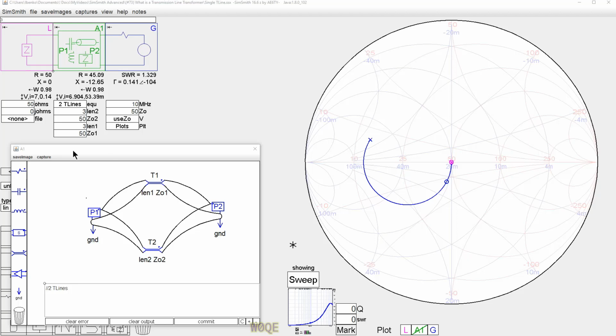The load impedance is set to give me no rotation. With a 25 ohm load impedance, these two transmission lines, 50 ohm and 50 ohm in parallel, give me a 25 ohm result, swept over frequency. So this acts as a 25 ohm piece of transmission line. What happens if one of these is a little bit longer than the other one?